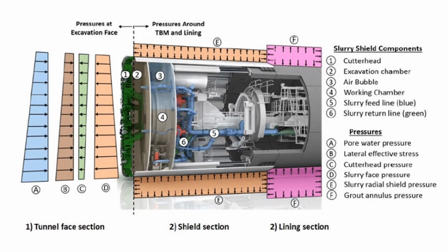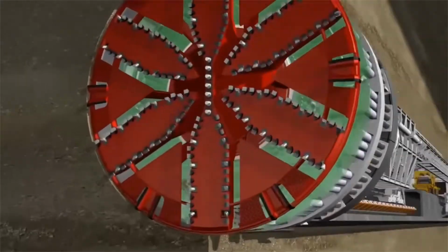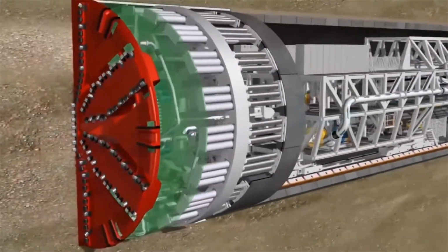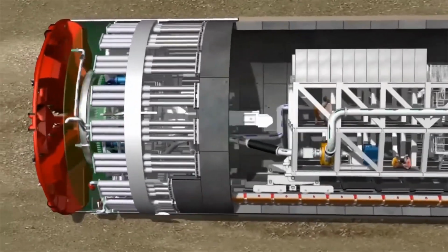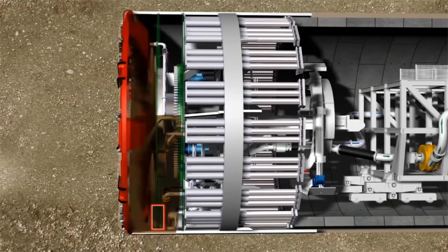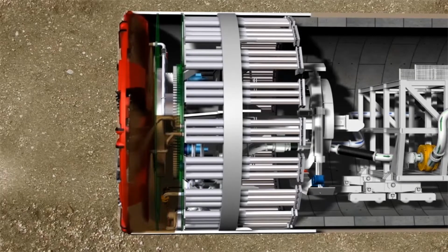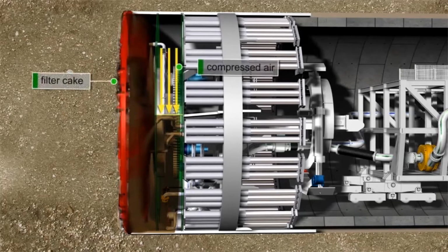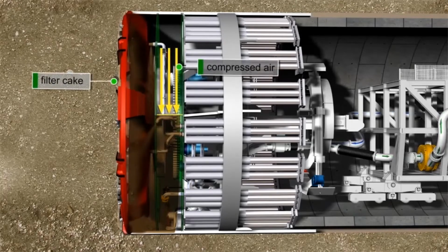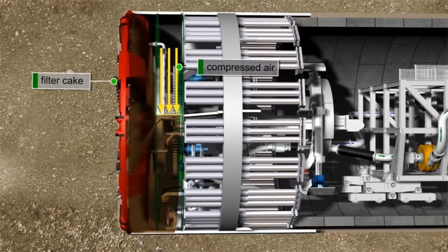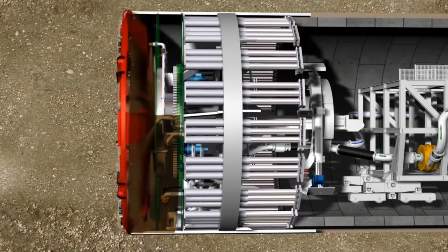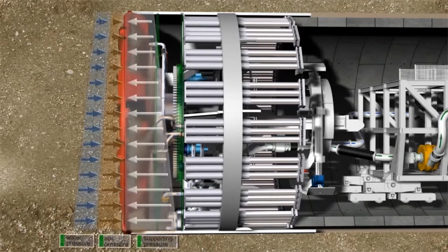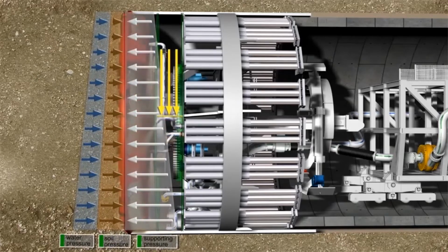Next, the components of the slurry mixed-shield tunnel boring machine (TBM). Generally, it consists of four main parts. The first part is the rotary cutter head with tungsten pick bits, made for excavation of soil, and these cutters for excavation of rock. Moving on to the second part, the bulkhead, positioned behind the rotary cutter head. During the tunnel excavation, a pressurized bentonite slurry barrier is formed to provide stability.